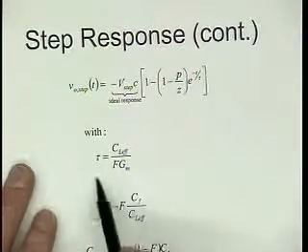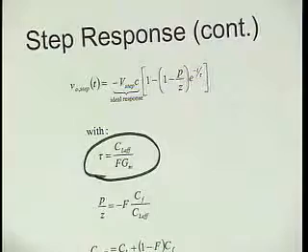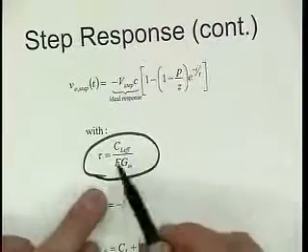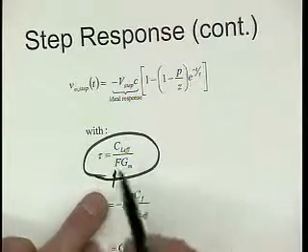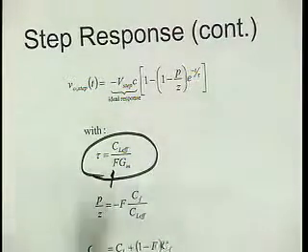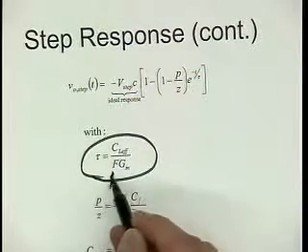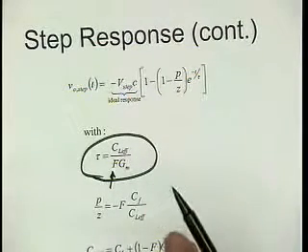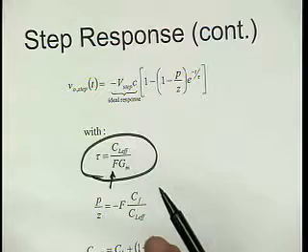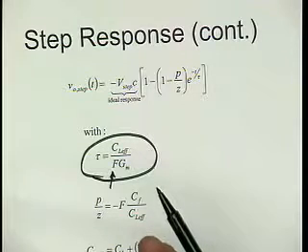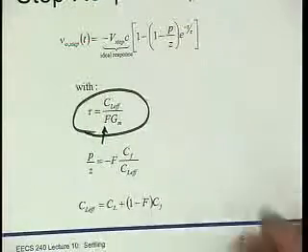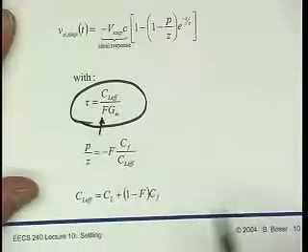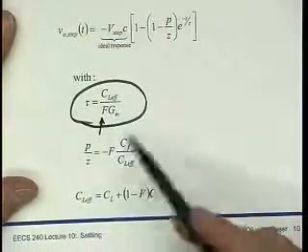So if we later want to have an amplifier that goes at a certain speed and settles to a certain accuracy, this tells us we have to figure out CL effective, we have to figure out CF, and based on that we can figure out GM. Then we can design the amplifier. And of course here we also see that this F term we really would like to be as big as possible, right? F is always less than unity. And then the ratio of the pole to the zero frequencies is given here.